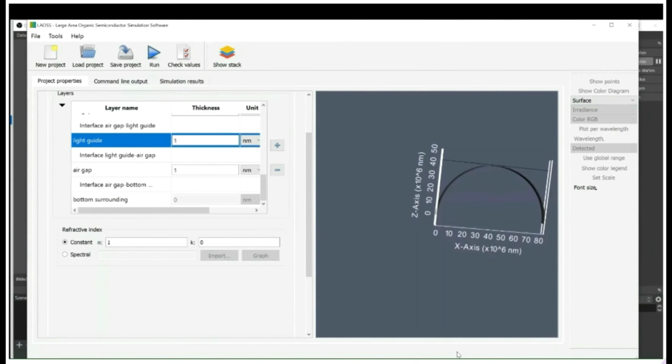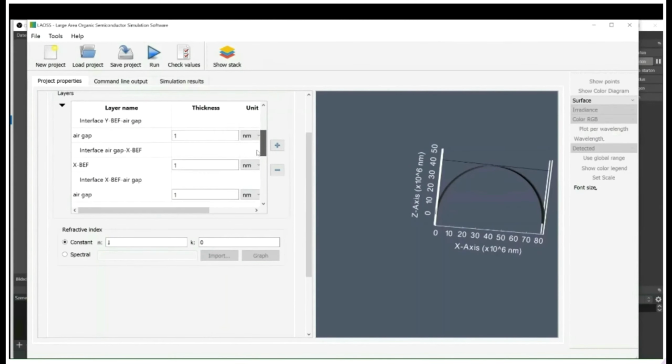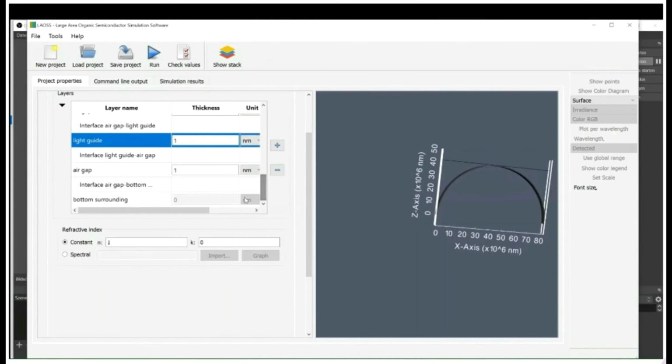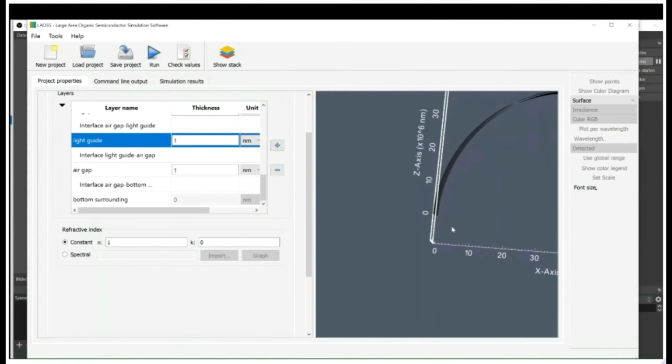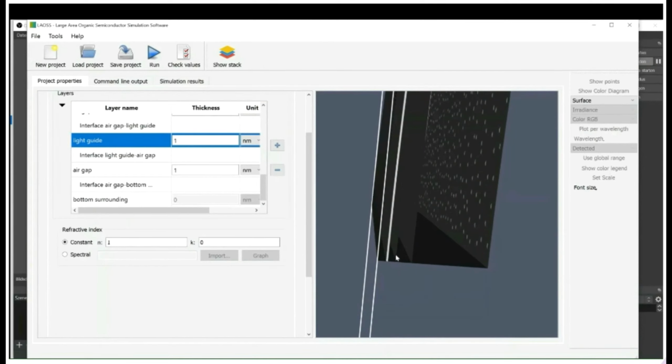We now consider a backlight unit with semi-cylindrical curvature. Geometry and topography files are again generated via a dedicated Python script. A curved geometry requires a slightly different approach to the setup of the layer stack. While the sequence of the layers and interfaces is still the same, most of the layers need to be defined with vanishing nominal thickness. As for a cylindrical curvature, the thickness is now along the radial dimension, meaning the position of the layer surfaces is given by the radii of curvature of the interfaces.